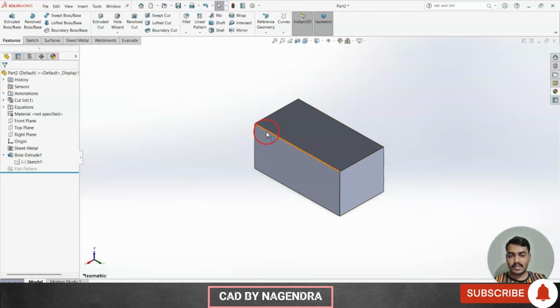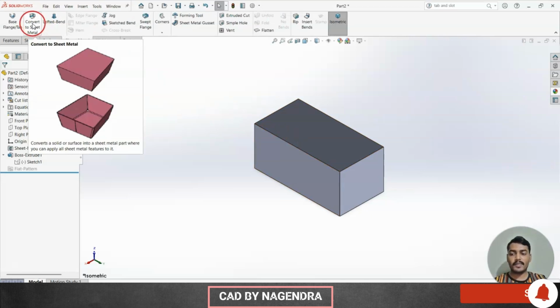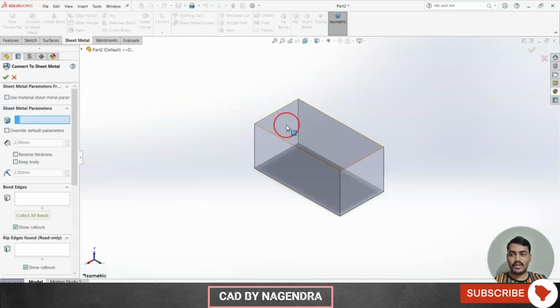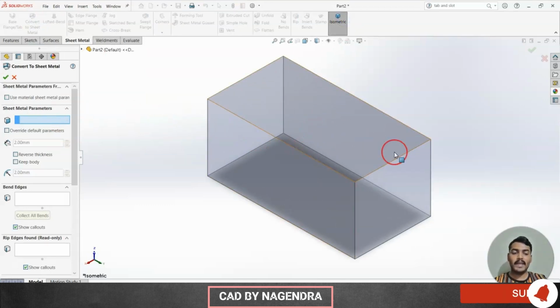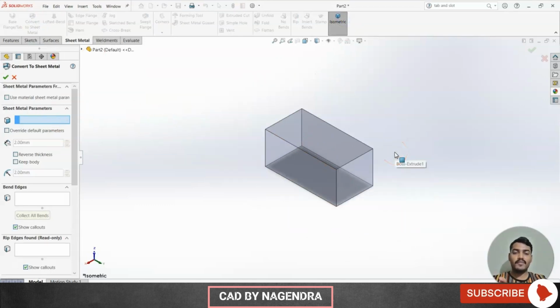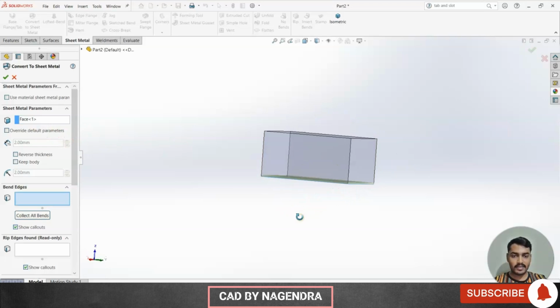In very rare cases we use this. In such case, we can use this option called convert to sheet metal. Just click on convert to sheet metal. Then we need to select here base, with reference to which face we need to create that entire sheet metal part. So this base I'll select as this bottom face.